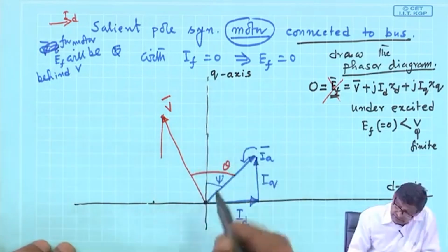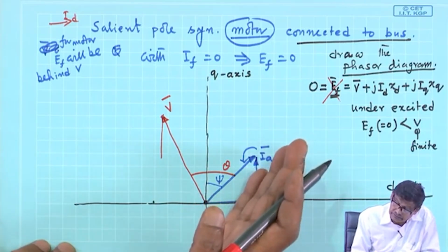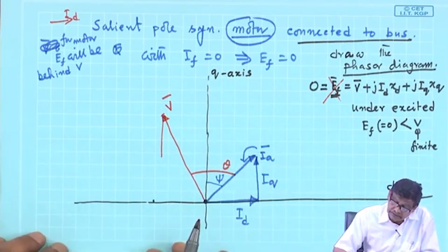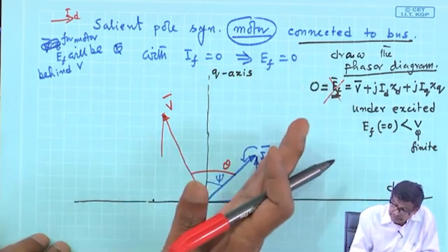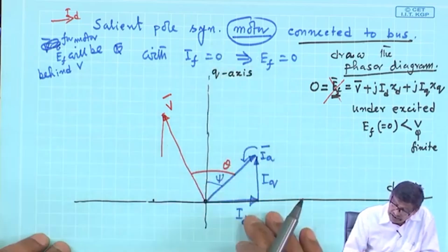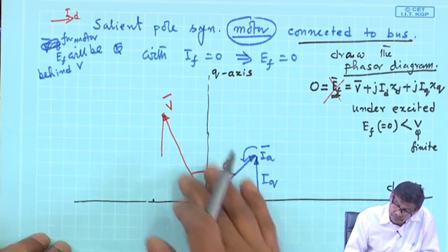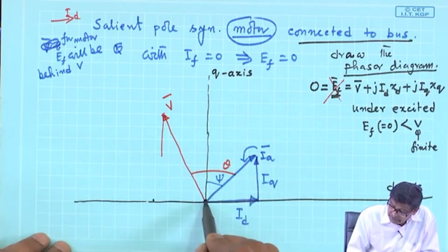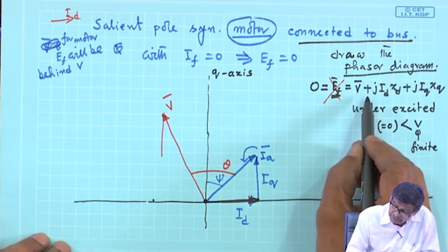So, this is q axis, this is Ef, this is armature current here, armature current here, and under excited means lagging power factor. So, q, Id, Iq you get, then in case of motor V should be ahead of Ef. These same arguments I am repeating, because I am facing some problem. So, this is the thing IdXd. Now, to this V you have to add jIdXd.